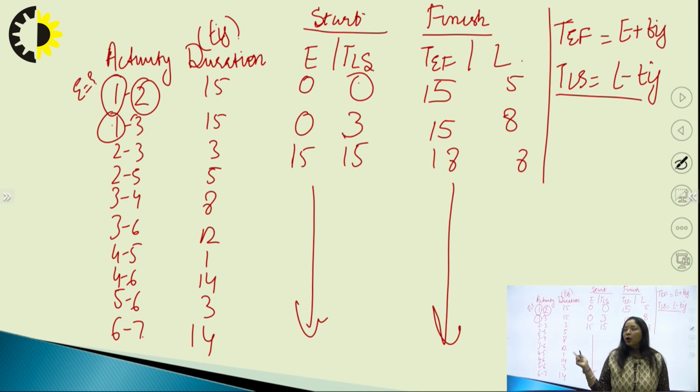How can we find it? We have to find out float. Float is the extra time which is given ahead in the activities where it can be compensated. It is the difference between the maximum time available to perform a task and the activity duration.